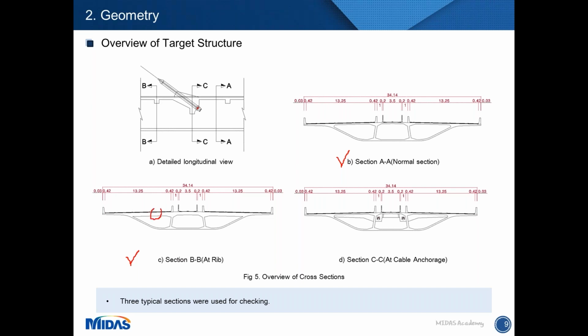So these are the leaves. Last one, section C, is the normal section with cable anchorages and leaves in each cell. I guess that there is a huge concentrated force in the middle of the girder due to the cable force. So additional leaves in the inner box here were planned to reduce the effect.